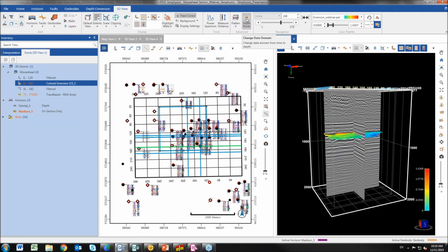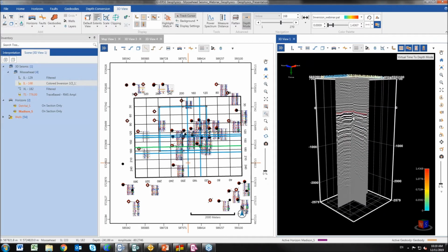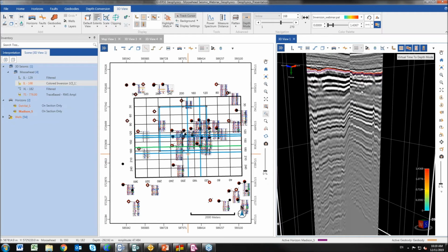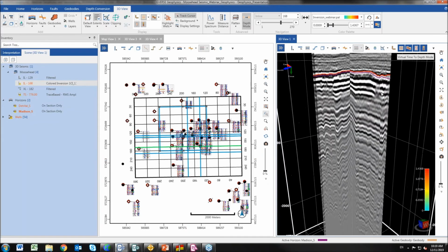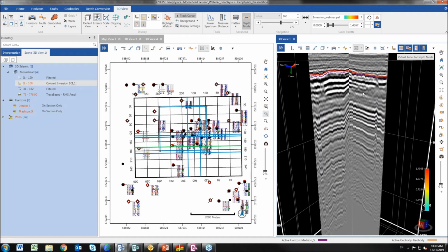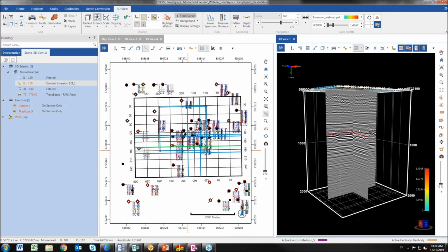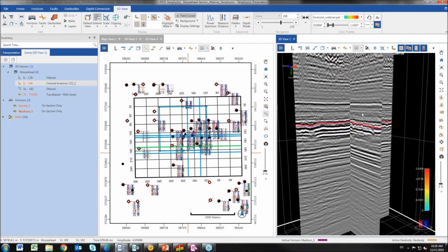And we click here the time to depth change domain mode. We just click on it and it automatically changes from the time domain, in which the interpretation was created, to a depth mode interpretation. So we can see the interpretation in depth mode to have an idea of how the seismic is going to look with a depth mode interpretation. We click it back and it takes my interpretation back to time mode.